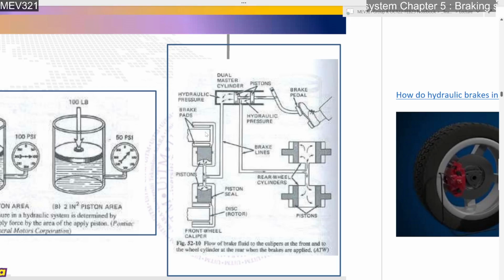found in your wheels. If you have the disc brake, it will push the pistons on the brake caliper and so on. So the brake caliper will squeeze your disc brake. So friction will occur, and the kinetic energy from your tyre, the movement of your car, will be converted from kinetic energy into heat energy. That's why the disc brake becomes hot when we brake.